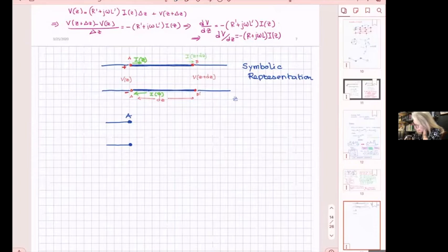And then here we have what we found. We have a resistance per unit length, R dz, which comes out of the ohmic losses of the conductors, and inductance per unit length L, which now I multiply with dz because this is the length of this line. I selected it to be an infinitesimally small length. We call it dz.